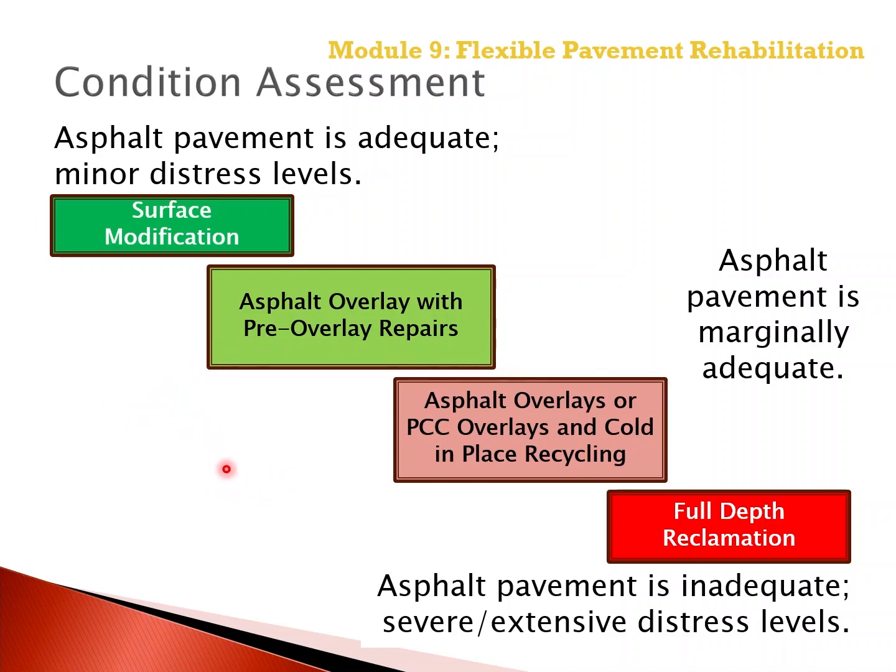As additional damage occurs in the asphalt pavement, and that pavement is considered weaker, asphalt structural overlays or concrete overlays and or cold-in-place recycling may be needed as a rehabilitation strategy.